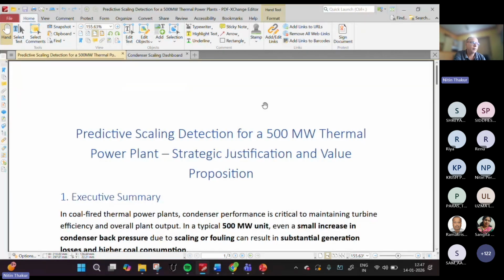It is an important one, because if throughout the year I'm doing this chemical treatment and tweaking it using, let's say, AI or machine learning, or we just monitor the active ingredient, and I'm getting the runtime before we hit the threshold of 60% scaling, and let's say we get that runtime extended to 2 years, that means I can run my power plant for 2 years without taking it out of service for cleaning or any maintenance activity, and keep that power plant efficient, with higher efficiency from fuel to electricity conversion, for 2 years.